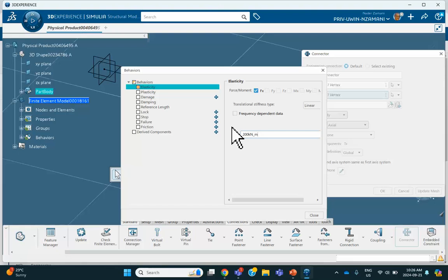So I don't understand this. All right. So what I'm going to do is I'm going to say 200,000. That means the kilonewton. You put 3 more zeros here and put an M there. Now this is going to get converted to Newton per millimeter, and it's going to give me the same number, 200 Newton per millimeter. Fine.